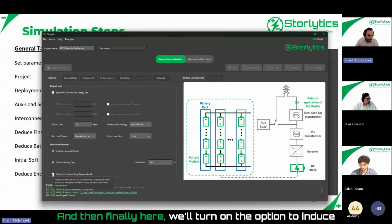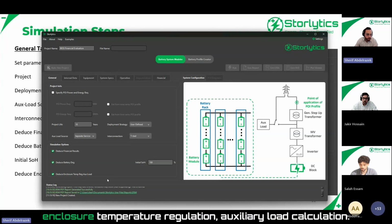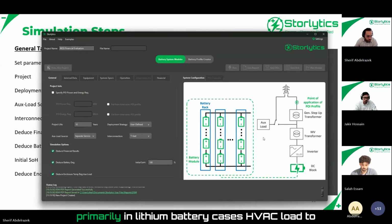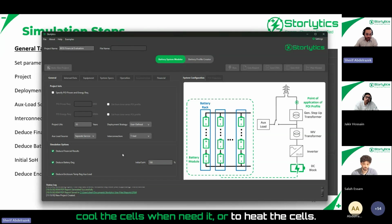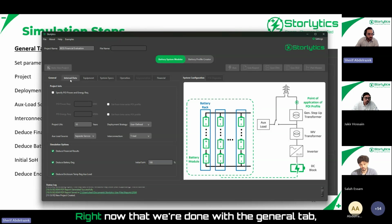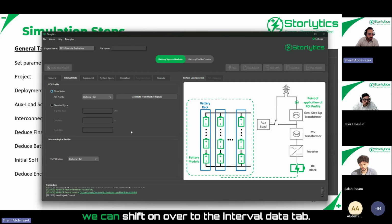And then finally here we'll turn on the option to reduce enclosure temperature regulation, auxiliary load calculation. And what this does is it allows the simulation to calculate what the auxiliary load will be, which is primarily in lithium battery cases, HVAC load to cool the cells when needed or to heat the cells. And if your project is in a cold environment, you'll need to heat the cells. So this option allows the simulation to do that automatically. All right, now that we're done with the general tab, we can shift on over to the interval data tab.